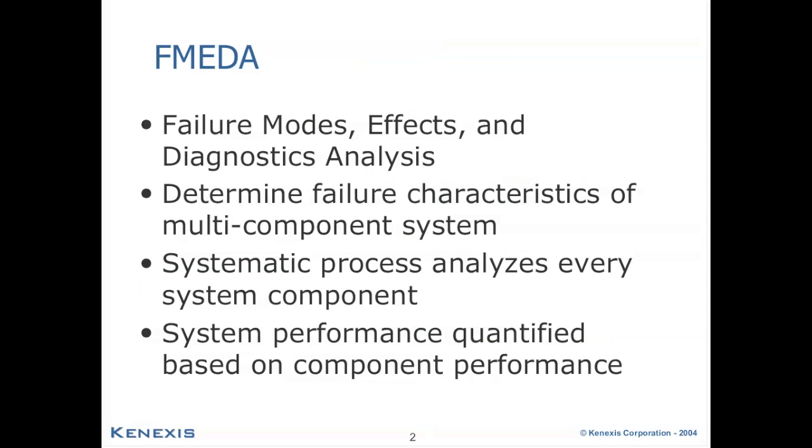The approach that we're going to use to calculate that diagnostic coverage is something called FMEDA, Failure Modes, Effects, and Diagnostics Analysis. This is something that we're going to do for a multi-component system, and in that system, we're going to systematically analyze every component in the system, looking at all of the failure characteristics of each component, and one at a time assessing how the entire system would respond to each different failure mode of each component.